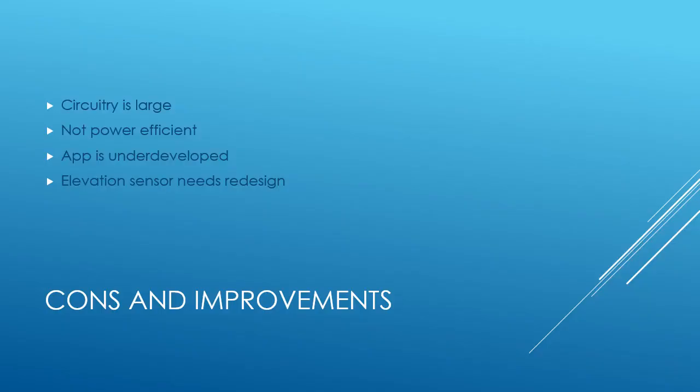Circuits take much more space than commercially available alternatives. To reduce the size, making custom PCBs with SMD components would drastically shrink the profile. Our design uses larger lithium-ion batteries compared to the coin cells commercial products use. To make our design more power efficient, communicating with Bluetooth BLE instead of Wi-Fi would be ideal.